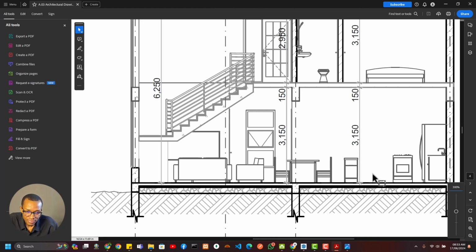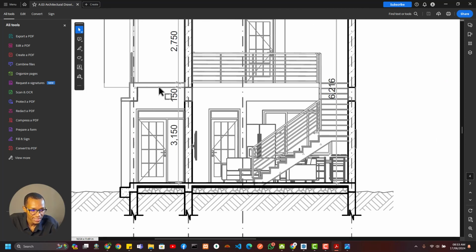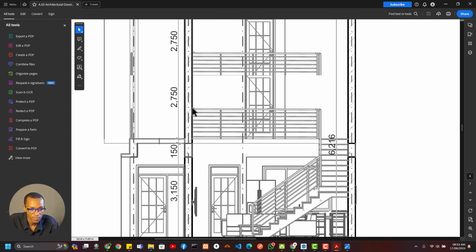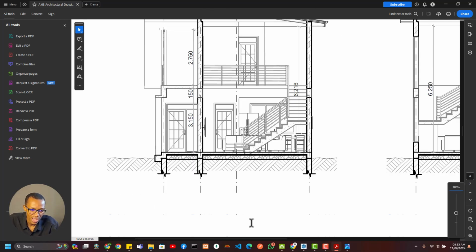You can see here, I can immediately tell that the height of this room is 3000. Typically the height of a room is 3000 millimeters. That's the typical height of a room space. I can also tell the thickness of the floor, when you have a floor above you, is usually 150, depending on this, but usually 150. So from this floor to the top of this place is 2750. All these pieces of information will come in handy when we start modeling.